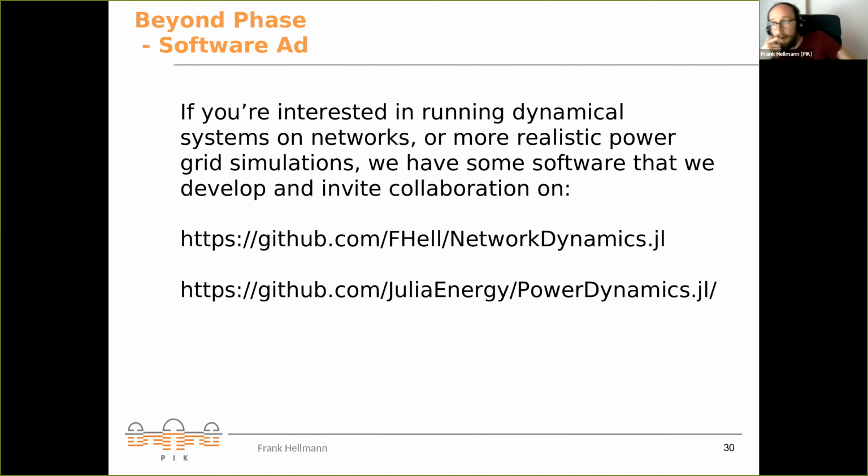Part of what we've been studying in the last 5-6 years, as you well know, is how safe is it to do this? How much might you be misled by taking the simple model? We know that, for example, having a parameter like the losses, that still fits into the Kuramoto model, but assuming the losses are small, which people used to do, can mislead you heavily. Not having the voltage dynamics, something we found with Sabine Auer in a paper, can really mislead you heavily about the fixed points and about the stability of fixed points.